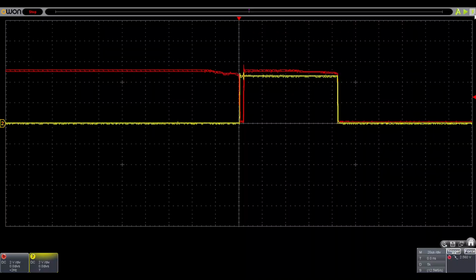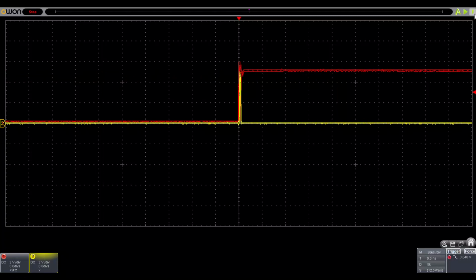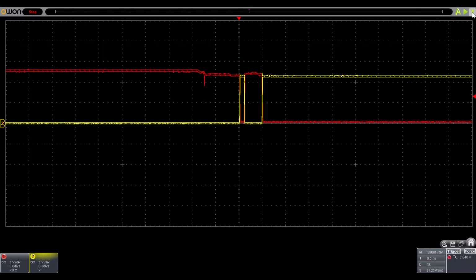This shot shows a brief spike 80 microseconds before the expected trigger, producing an erroneous double trigger. The next shot shows ringing, which caused 2 state transitions erroneously on the rising edge. The third shot is a particularly ugly example of an unexpected spike and ringing, leading to 2 unwanted state transitions in addition to the expected edge trigger, all occurring within about 200 microseconds.